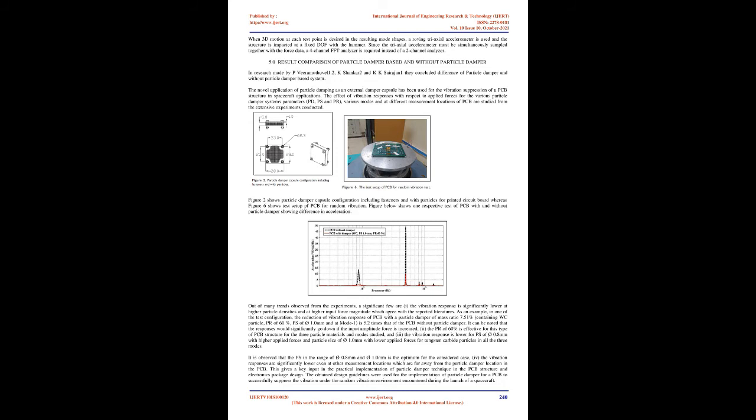In practice, the force and response are usually measured as functions of time, and transformed into the frequency domain using a fast Fourier transform, FFT Analyzer. FFT transforms a signal from time domain representation into its frequency domain representation.